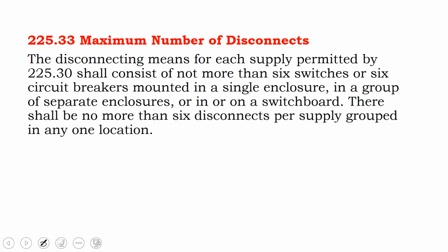If you only have 6, then 6 is considered what you can do in a short period of time to turn off all the power. 7, that's the cutoff. It's too much. And so you can have 6 inverters going into a transformer. If you have 7, you need to have a main disconnect switch. You could have 14 inverters going into 2 main disconnect switches going into a transformer. You could have 6 different backup power supplies. If you have 7, you need to combine them all into one panel and have one main switch.